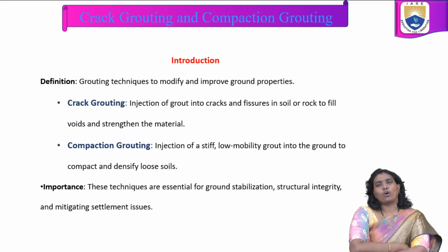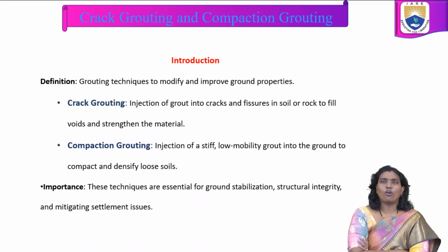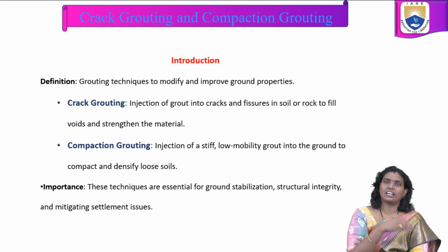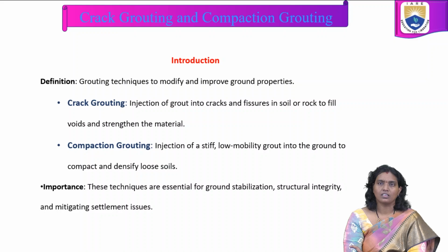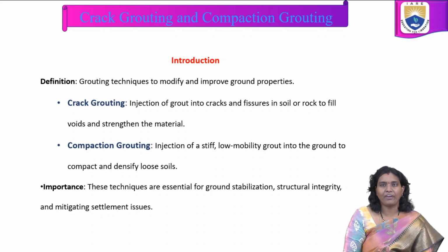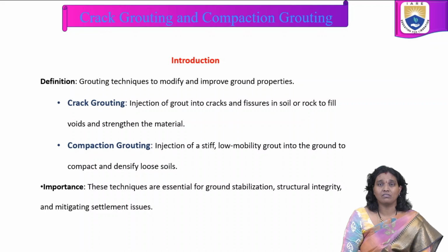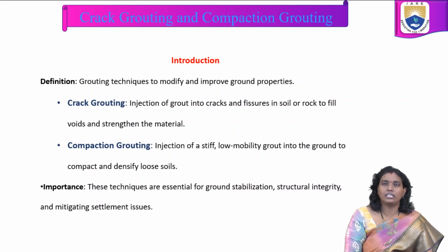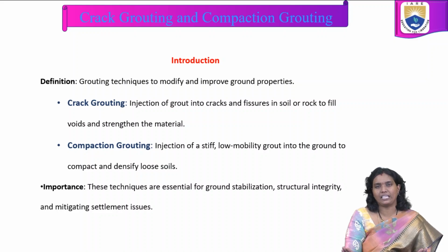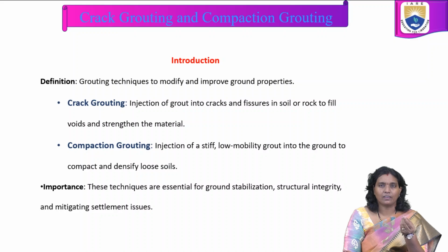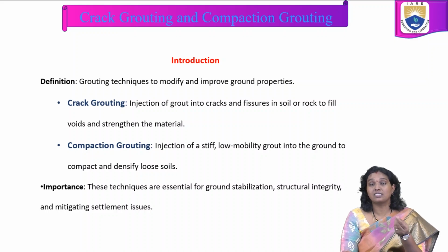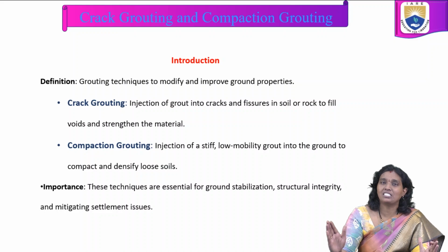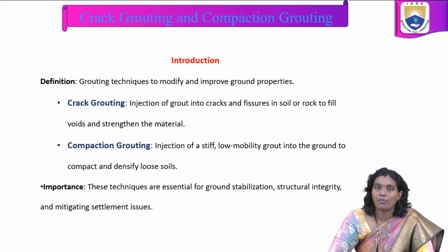So as a part of ground improvement techniques, understanding crack grouting and compaction grouting is important. In these grouting techniques, we modify and improve ground properties. Coming to crack grouting: injection of grout into cracks in soil or rock to fill voids and strengthen the material. Whenever small cracks are there that may affect the strength, stability or any property of the structure, we use this type of grouting.